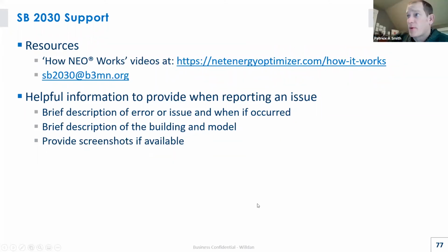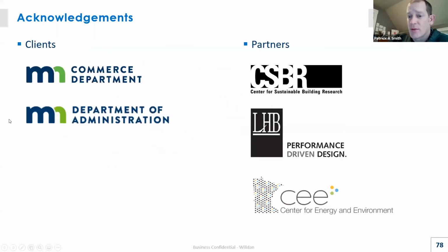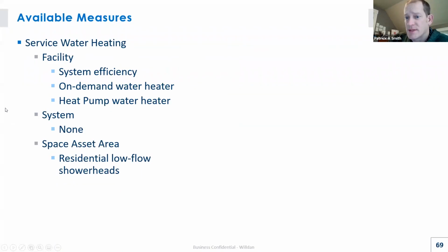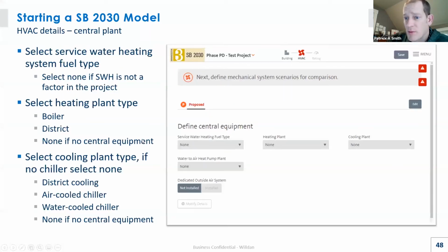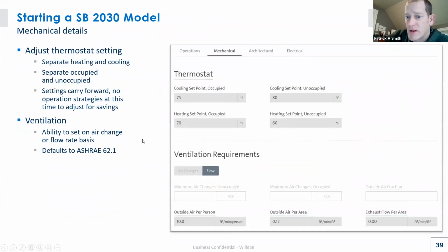Yeah, we've got a couple. There was a question about addressing air CFM per square foot versus ACH. Yes. My understanding of that is the tool actually doesn't just convert between the two. It actually runs them separately. So if you identify you have a certain occupant density, it's multiplying that by the number of CFM you have per person. It's multiplying the number of CFM you've identified per square foot by the identified square footage. And it's also taking the volume and running the ACH on that.